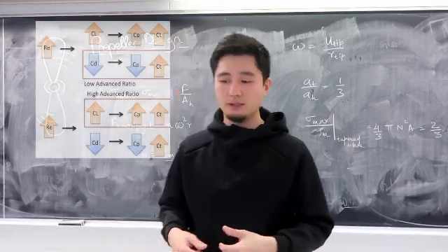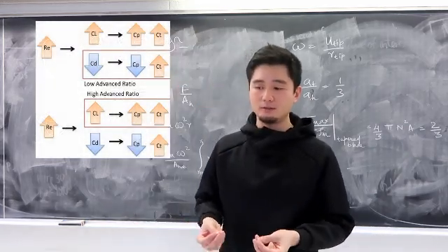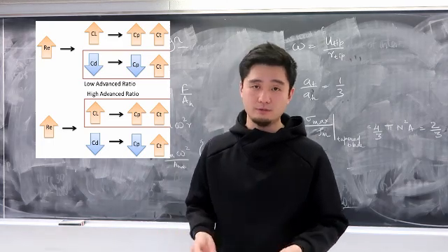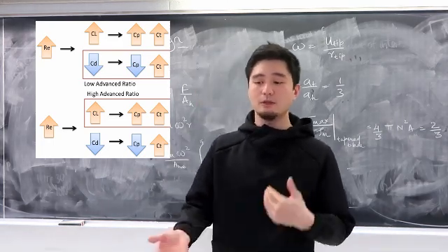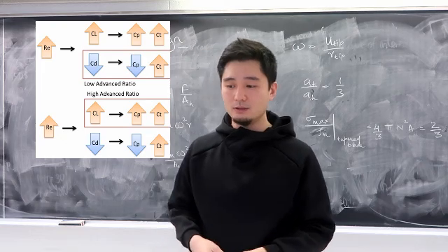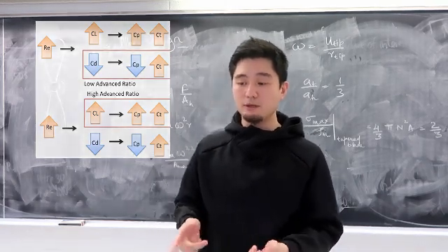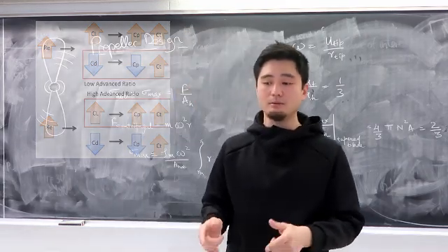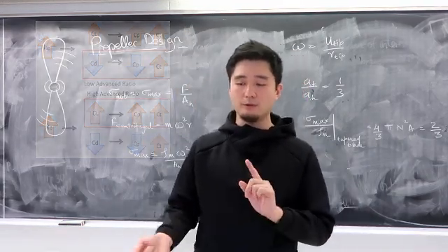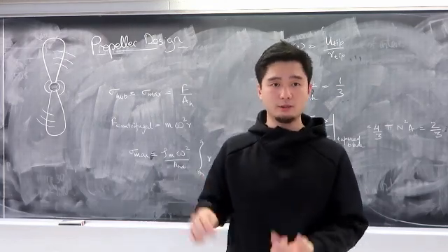Lowering the drag coefficient and raising the lift coefficient both have a positive effect on thrust coefficient, which is an increase in thrust coefficient. But the other way around is not true. Lowering the drag coefficient causes a decrease in power coefficient, but a rising lift coefficient would cause an increase in power coefficient. So the effect on thrust coefficient and power coefficient is the opposite.